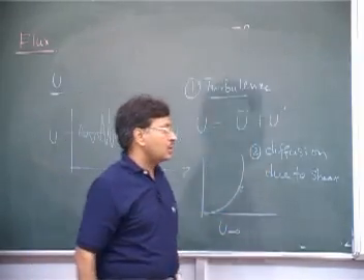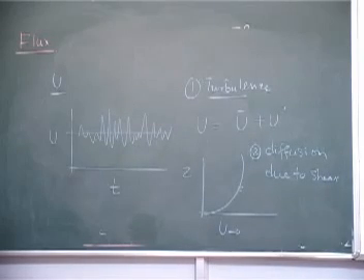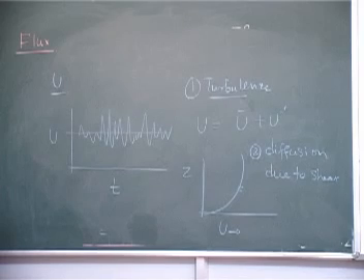If I have turbulence and diffusion, you can still use Fick's law, because this will still hold, but what will change is D, because D will no more be molecular diffusion alone in the atmosphere, but a combination of molecular diffusion plus turbulent diffusion or the diffusion due to shear and things like that.